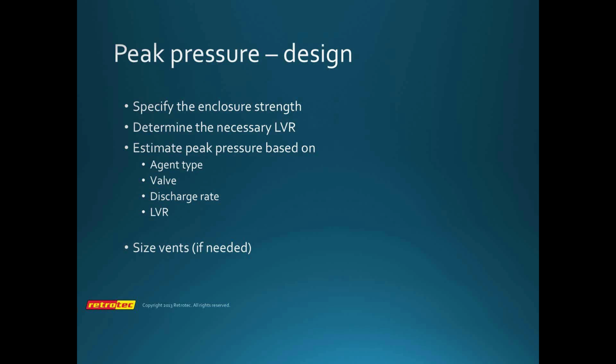But we do have a table that I believe I have in the presentation that has some appropriate values, and a typical 2x4 wall will take around 250 pascals or 5 pounds per square foot, and a well-constructed 2x6 wall with sheetrock on both sides and pinned at the top and bottom, meaning that it's not a free-floating wall, it's attached to the slab above and slab below, will quite easily handle 500 pascals, and we've had these walls up to 1,000 without too much of a problem.